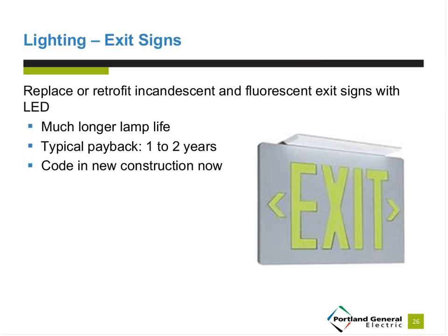A lot of customers don't think about their exit lights. That's a great opportunity to change from incandescent or even fluorescent to LED. Incandescent lasts you 2,000 hours, a fluorescent lasts you 10,000 hours, but an LED lasts you 50,000 hours. That's 6 years. So it's a great way, not a huge energy saver, but they last longer, and all the changes that you make add up over time.